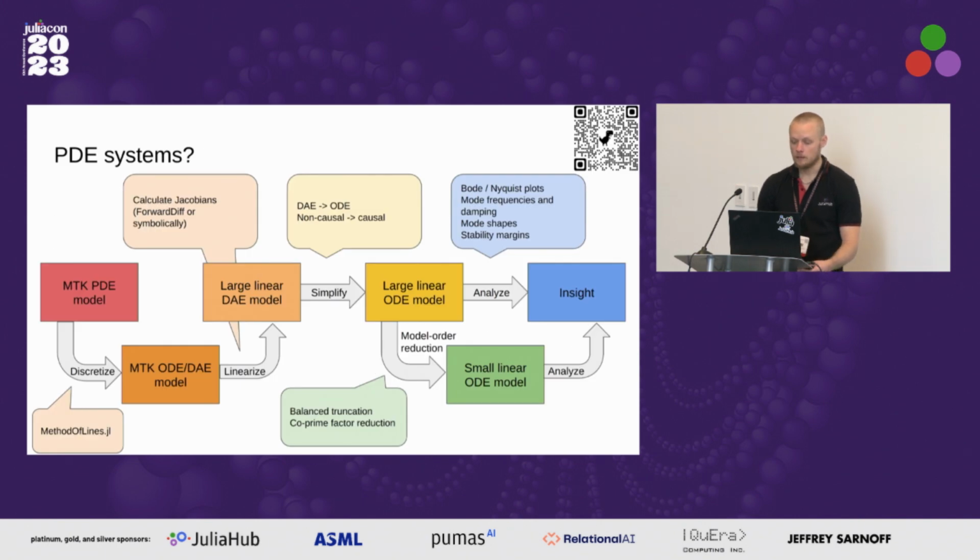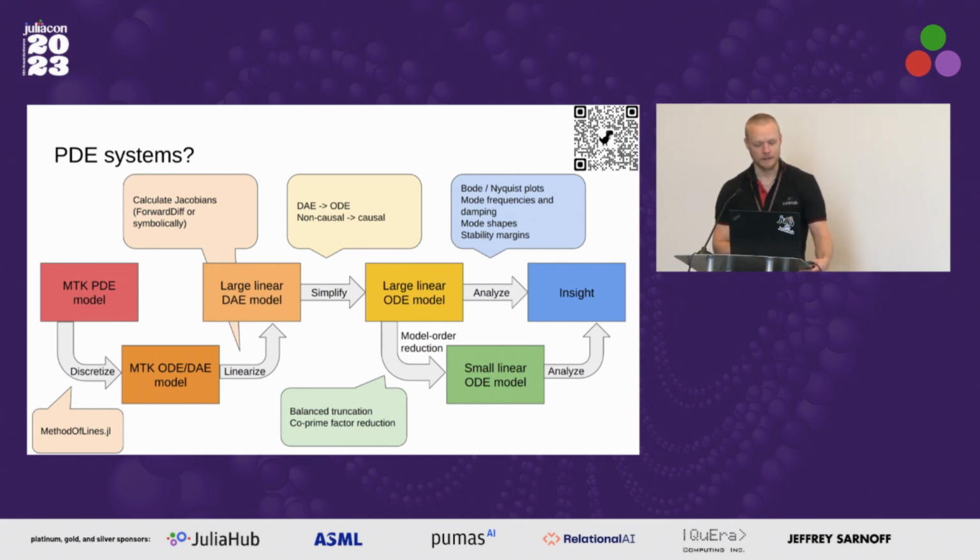All right, can you use this for more interesting systems, perhaps like a PDE system? And the answer is yes, you can, and now the path is slightly more convoluted. We will not dive into great detail here, but we can model PDE systems in ModelingToolkit. We might be interested in discretizing them, for instance, using method of lines. And after that step, we typically have a very large ordinary differential equation. We might want to linearize that, and then we have a linear version of that ODE.